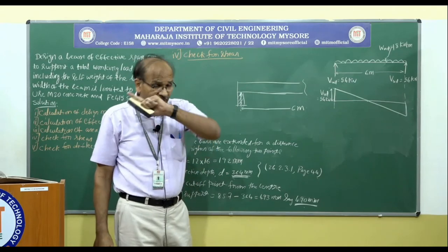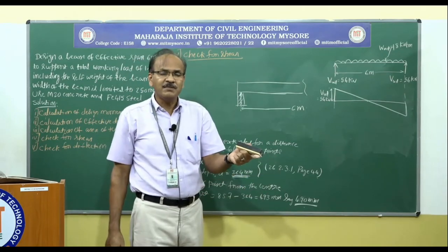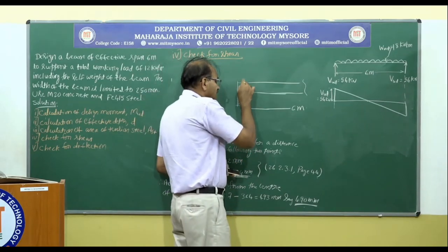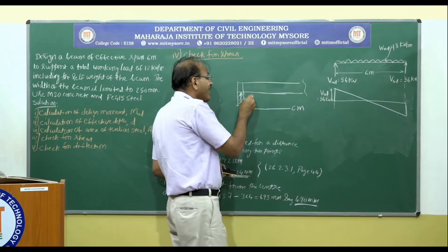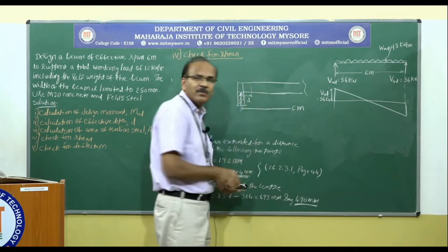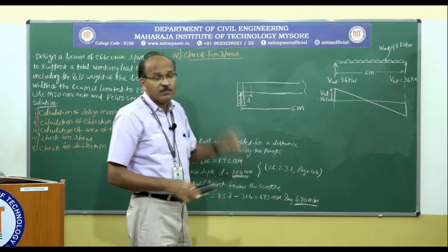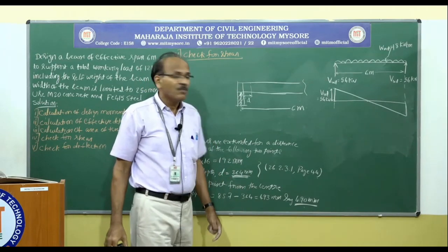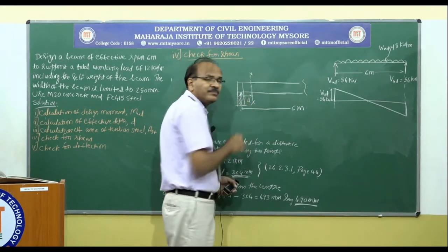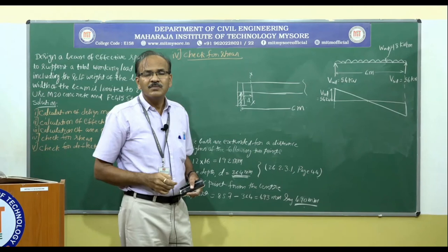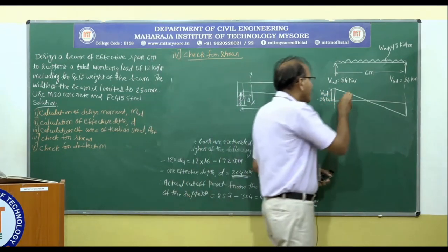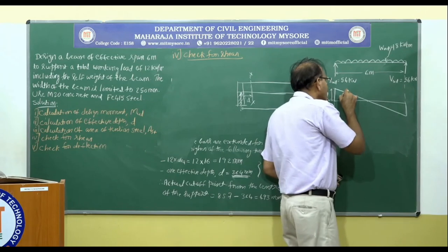However, as I explained in the first class on shear, we should not consider this face of the support. Instead, we should go for a distance equal to d from the face of the support. Okay, and that's where you must consider. Okay, and take that section and come here and find out what is the shear force here.